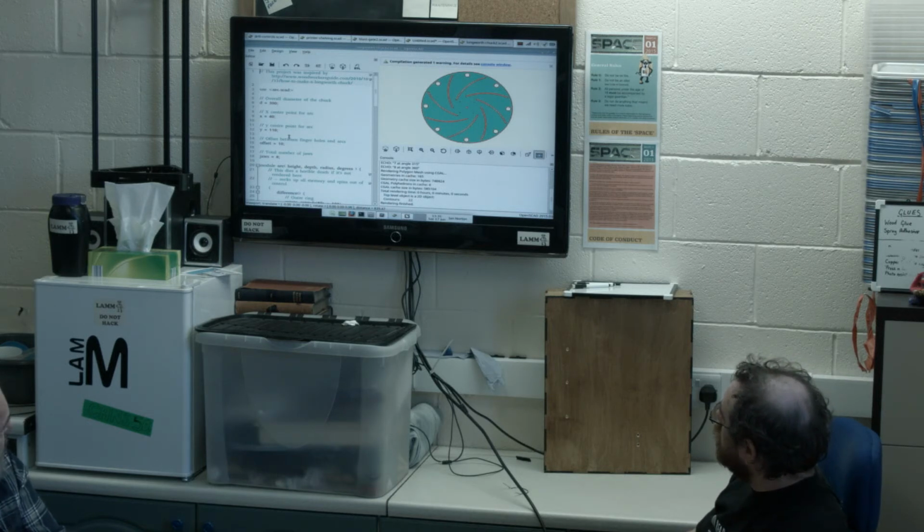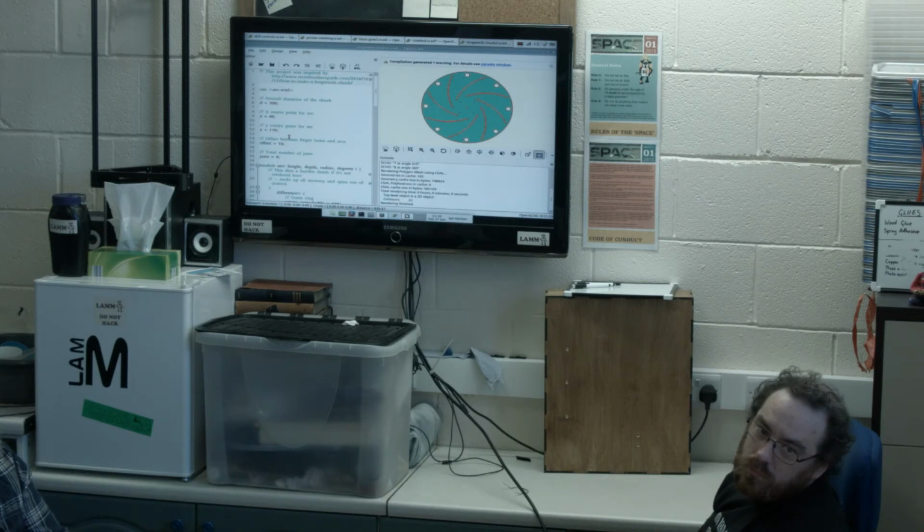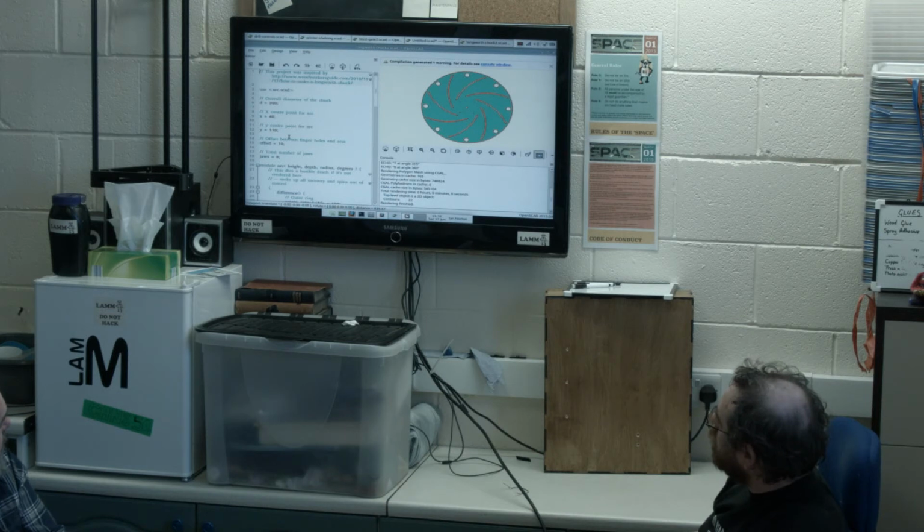It's the only thing that I really love about FreeCAD, once you get your mind around the fact that you can put all the numbers you're going to use at the top, and then build your 3D model around those variables, which makes more sense, because a number is a number is a number. A name is more relevant than just a number. And apart from the ease of remembering, you don't need to remember the number, you just need to remember the name that you give to the number.